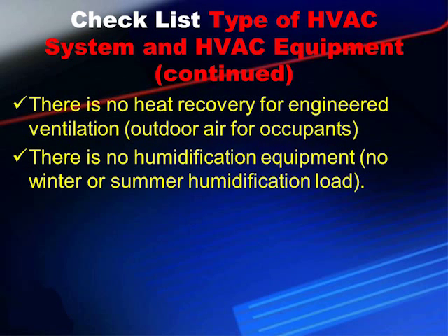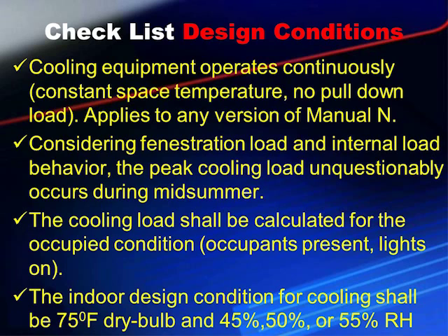Type of HVAC system and HVAC equipment. There is no heat recovery for engineered ventilation, outdoor air for occupants. There is no humidification equipment, no winter or summer humidification load. Design conditions. Cooling equipment operates continuously, constant space temperature, no pull-down load. Applies to any version of Manual J.